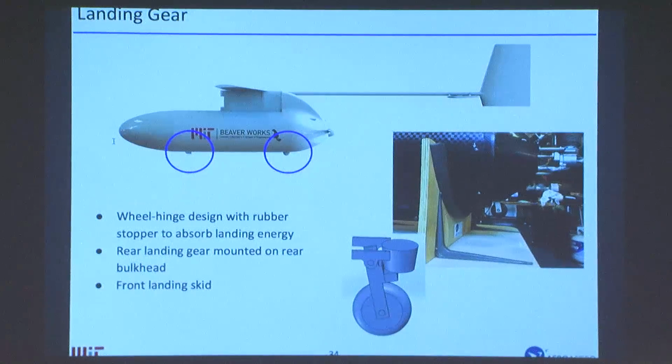And for landing, we intentionally kill the engine. Once we get on final, and we're assured a good landing, our pilot has a button that kills the engine. It preferentially stops roughly horizontally so we don't strike the prop, and we come in for a landing. We had to grapple with a lot of issues, and early on we weren't sure what we were going to do about the propeller, and whether we needed landing gear that makes enough room for the propeller. That would add a lot of drag, and this is how we solved it, with this simple scheme of just stopping the propeller.